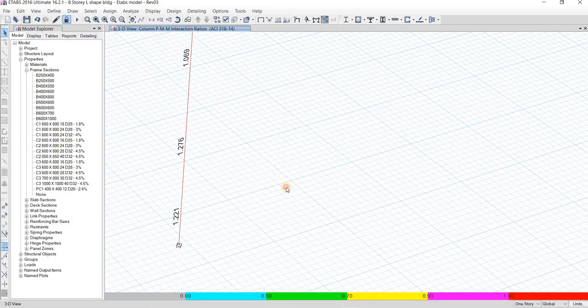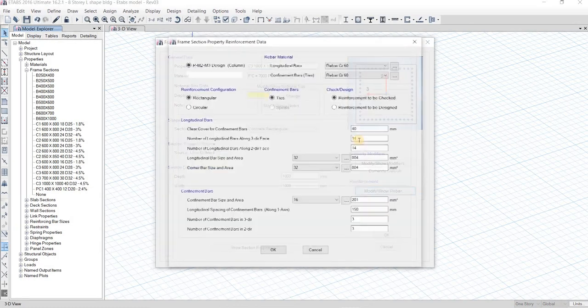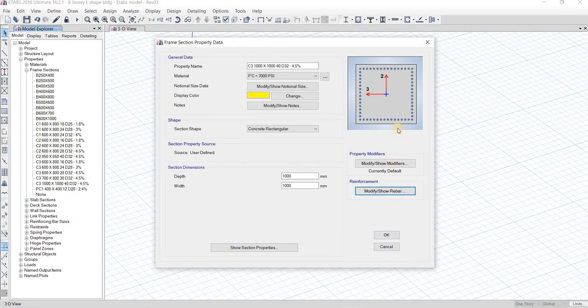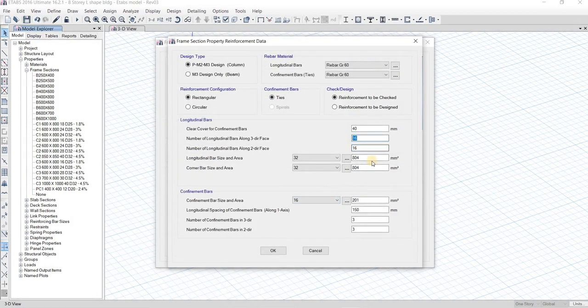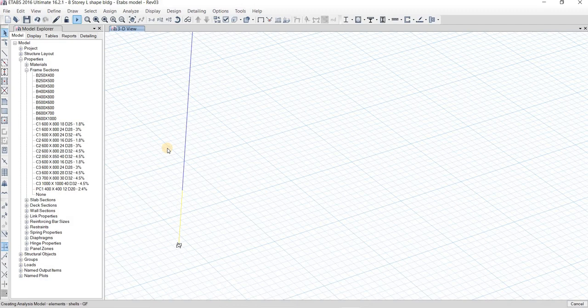So okay, you can also bundle this rebar. You can bundle that one. Okay, so I will just input a higher value. You can bundle that one, but you have to maintain the rebar percentage to avoid congestion. You have to follow the code restrictions.